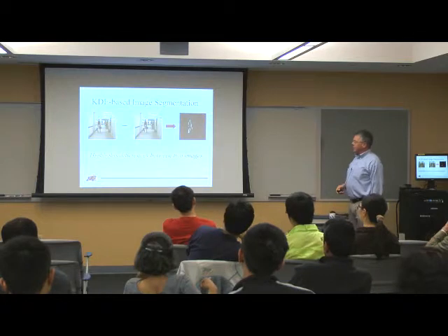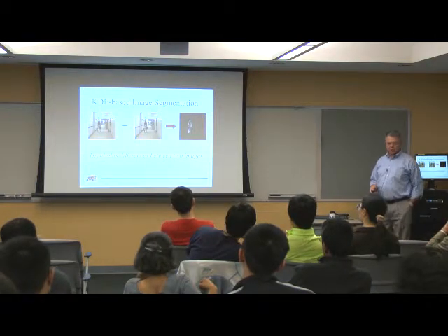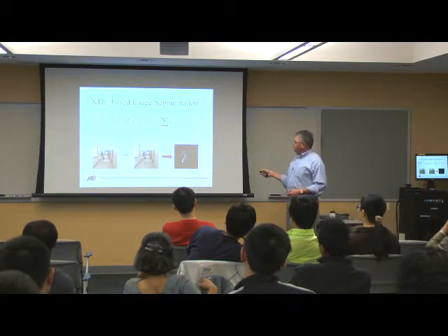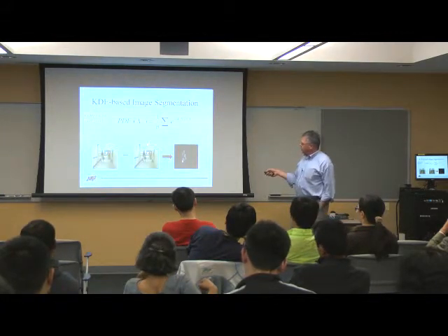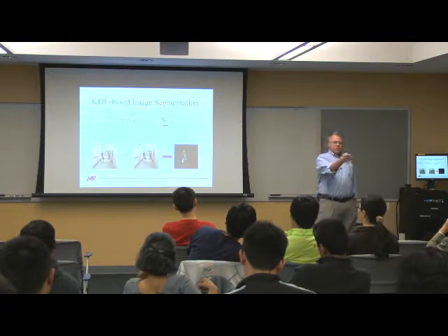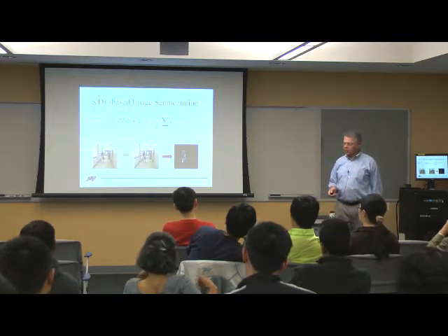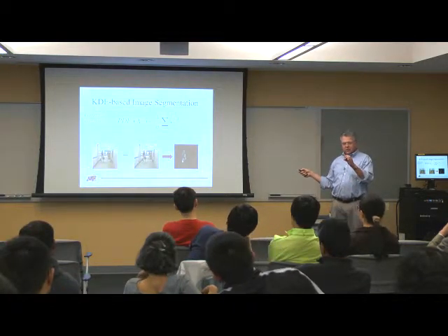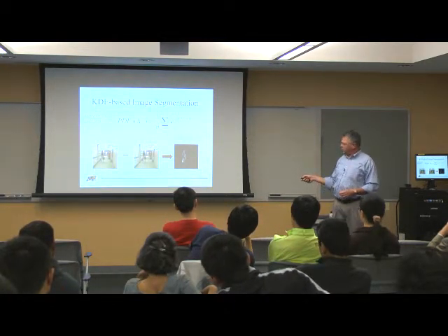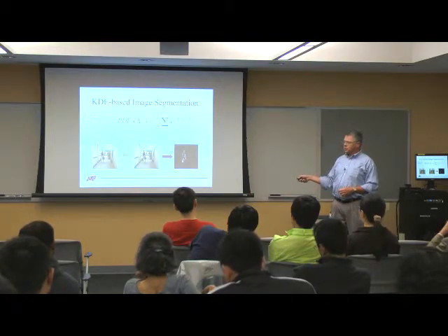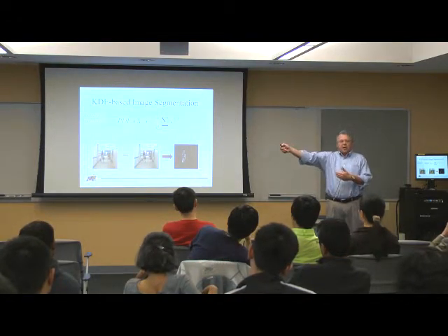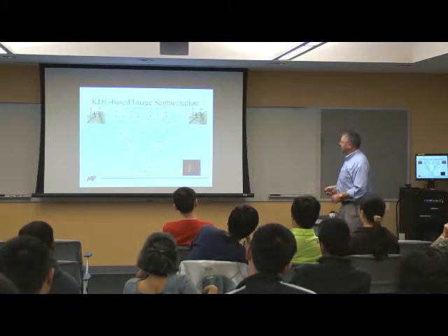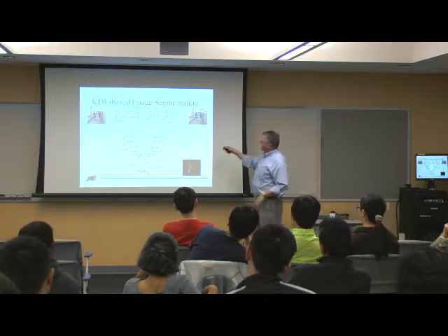Okay. This one's a little bit more interesting. This is a kernel density estimate. This is the example that I showed earlier. It's actually a little bit more complicated than what I said previously. What I really do is take the current image and n images back, however far back I want to go, and I compute this density estimator for each pixel, and then I do a thresholding operation to say, is that changed or not changed from this image back n images, where I have an exponential decay across the n images back. The circuit looks like this.